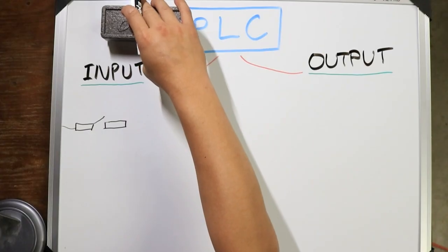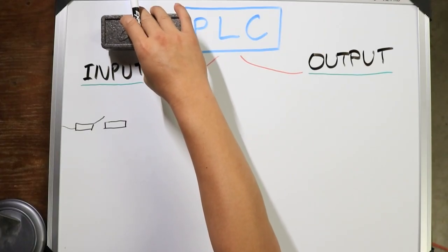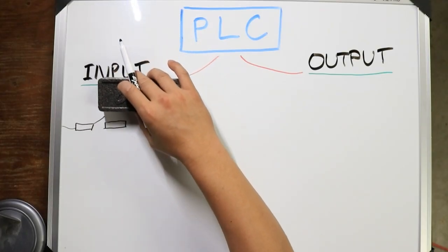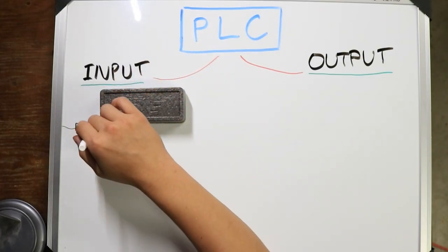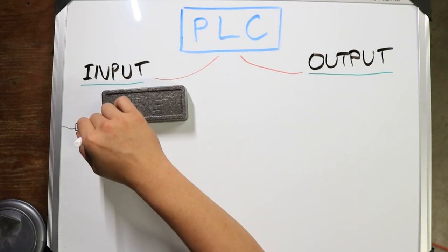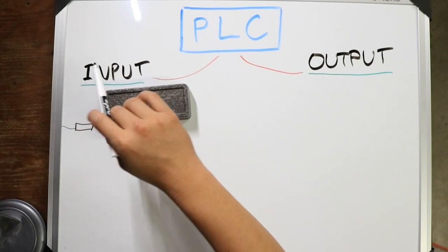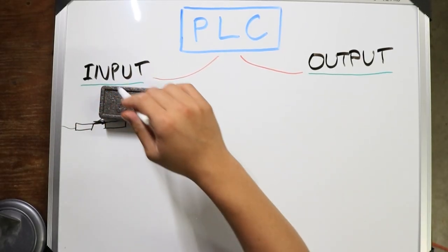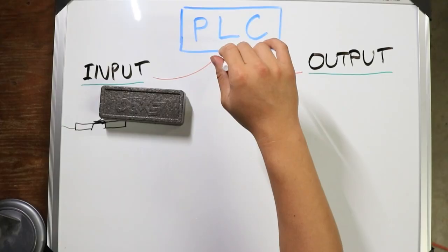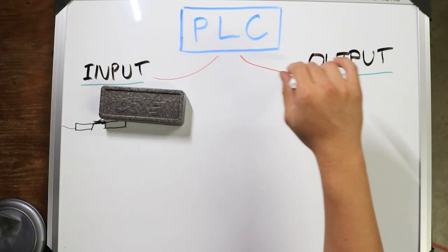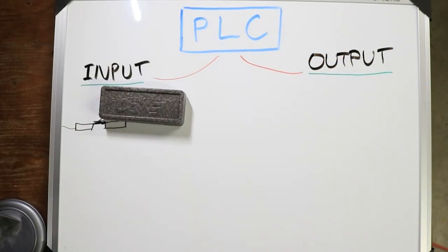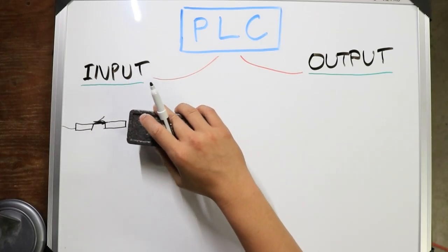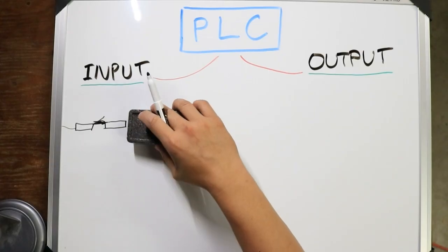And then the pallet comes, same concept. When the pallet gets there, we want it to physically stop the conveyor. Runs down, runs down, runs down, boom. It hits the lever, it moves down. Now it creates contact with the other side, which turns on. Once this turns on, the PLC reads it as on, and it will send a signal to an output to make something else work. So that would be a mechanical input.